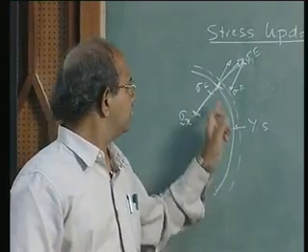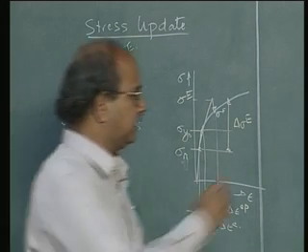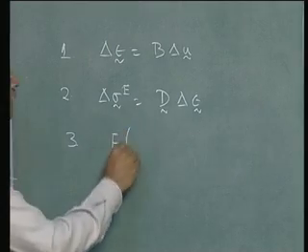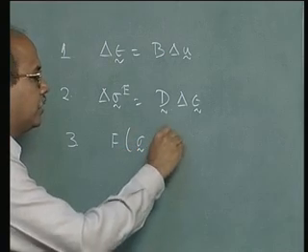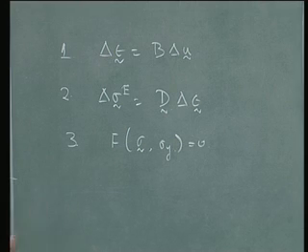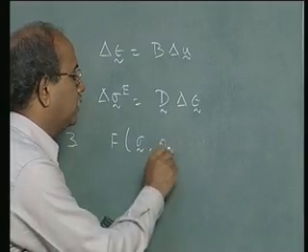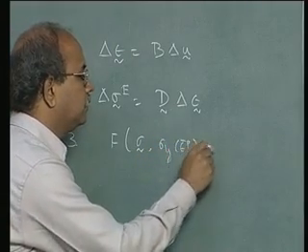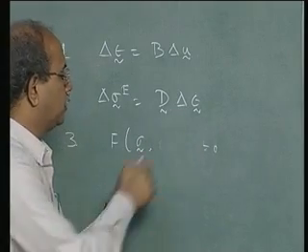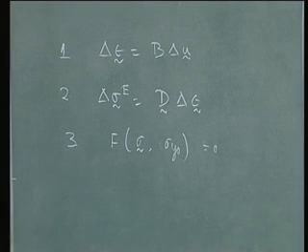It's very simple. I know the equation for the yield surface. I had already written down that equation as f of sigma comma sigma y0 is equal to 0. Of course, after first hitting the yield surface, sigma y becomes a function of epsilon bar p, that's equal to 0. But right now, for the time being, we have still not come to that stage, so I'm just putting that as sigma y0 only, because we are going to cross the yield surface for the first time.